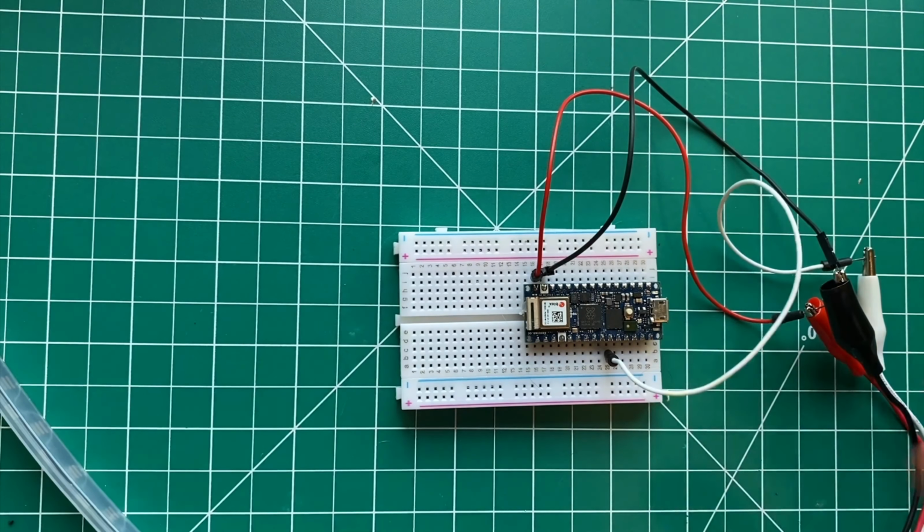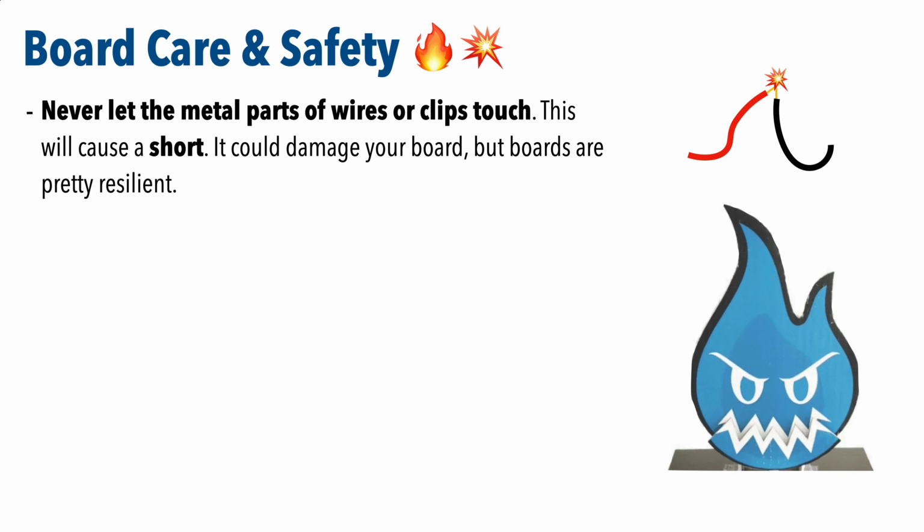And before we plug our board into our USB cable, now's a good time to review some board care and safety tips. So first, the metal parts of wires in your project should never touch. If that happens while the board is powered on, the board could short out. Now, if that happens, it's unlikely to damage your board, although that is possible. So you definitely want to make sure the metal parts of the wires are not touching.